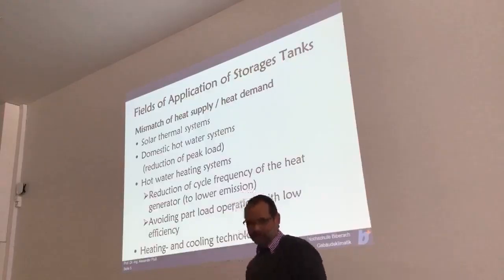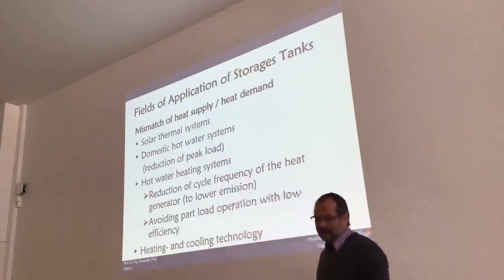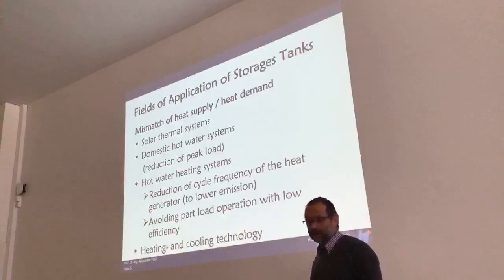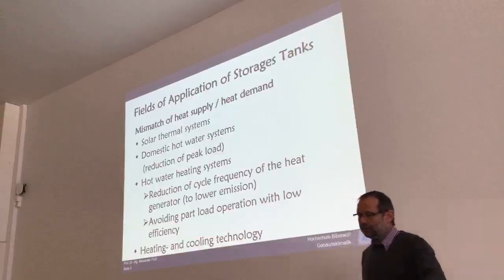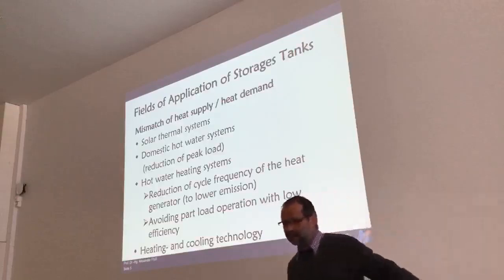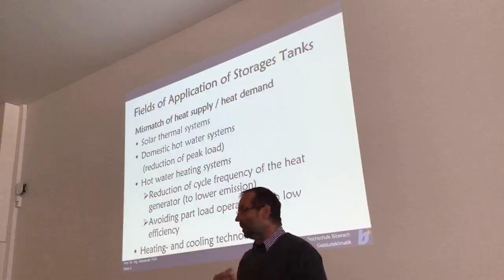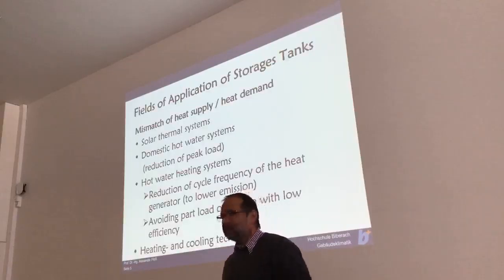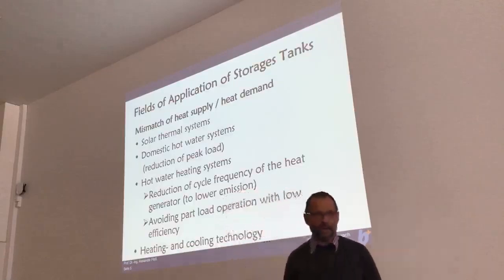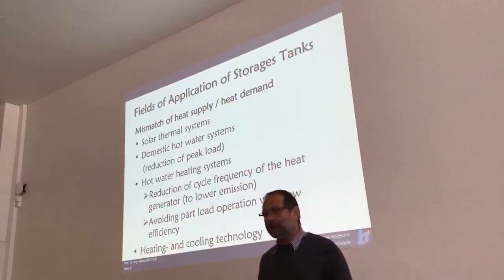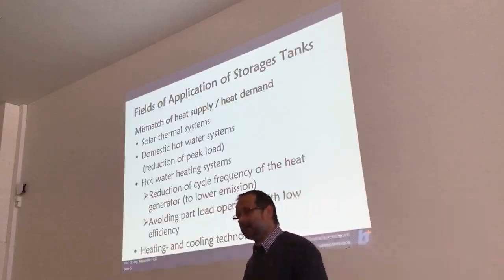heat somewhere. Another thing is we use storage tanks also in hot water heating systems to reduce the cycle frequency of the heating generators. That means the switching on and off of the heat generator. Especially, for example, combined heat and power stations, CHPs, it's not good for them if they have to start too often.